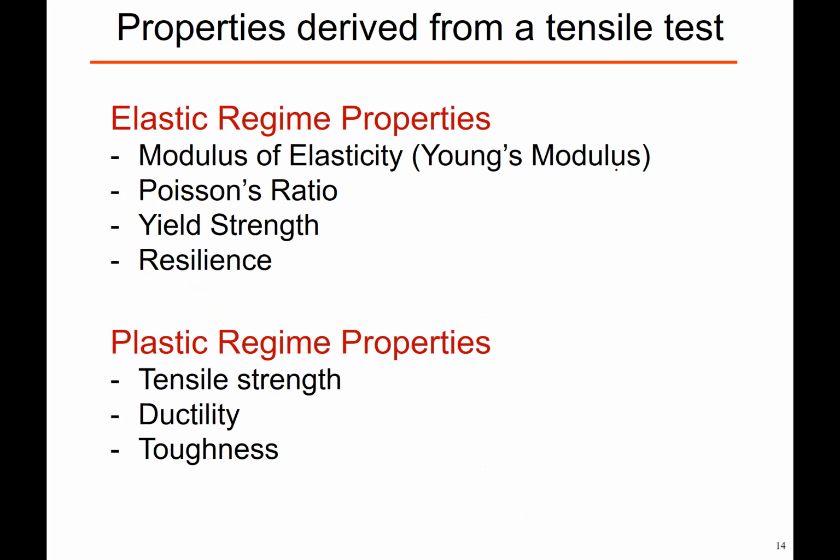Okay. So when we do these measurements, in terms of testing, let's say tensile stresses, we're really delineating the elastic region from that of the plastic region, right? If we apply a load and we release the load, in the elastic region, we can get the material back.